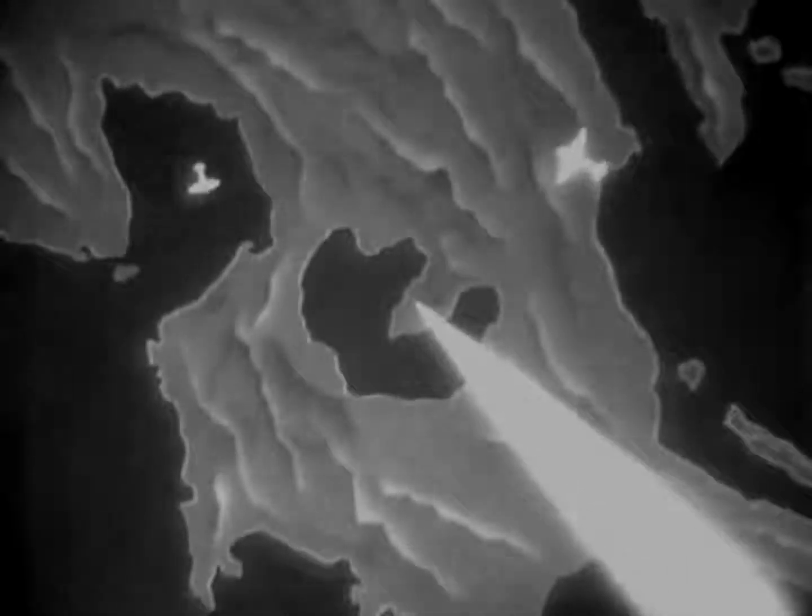And there's a target. See it there on the search scope at the right. To find the target's range, you have to stop the antenna and bring it back onto the target. Then crank the pip into the notch on the range scope. To get the azimuth, the pip must be split and balanced on the azimuth scope. Only after you've made these adjustments can you report the range and azimuth of the target. But while you're doing all this with every target you pick up, what about planes in other sectors? As long as the set is looking in one direction, it's blind to everything else around it.